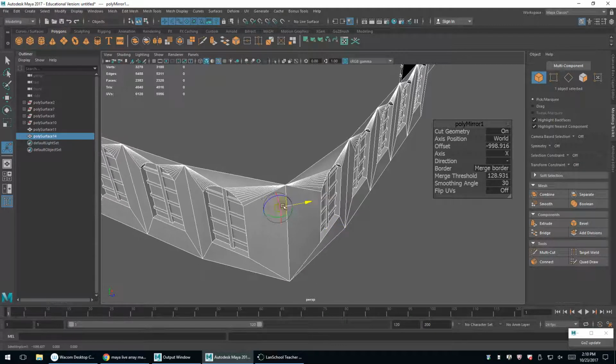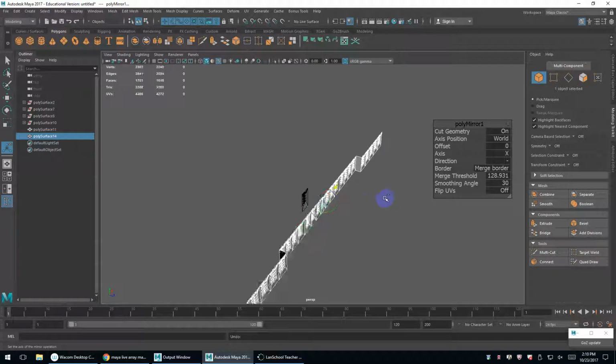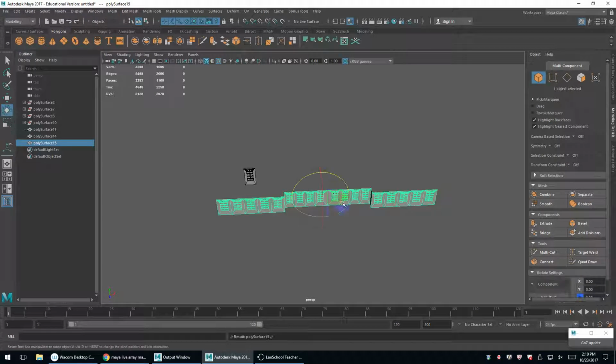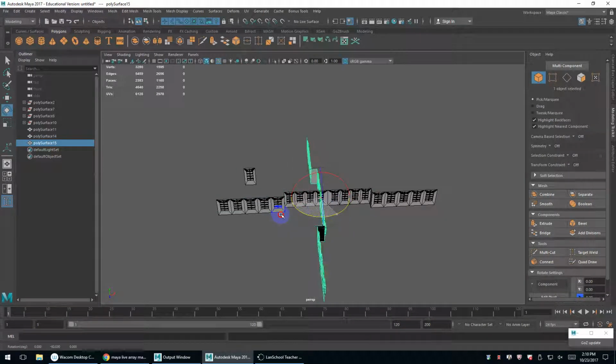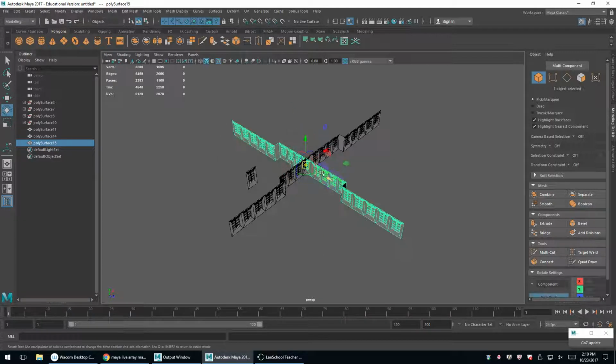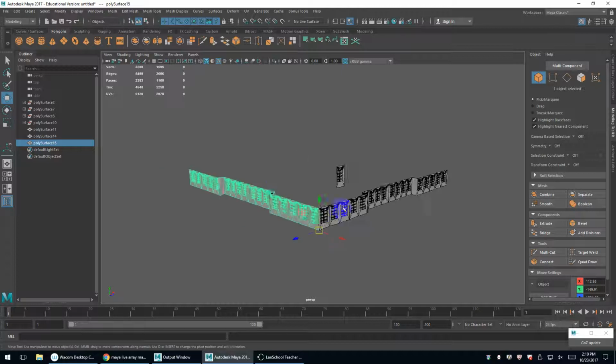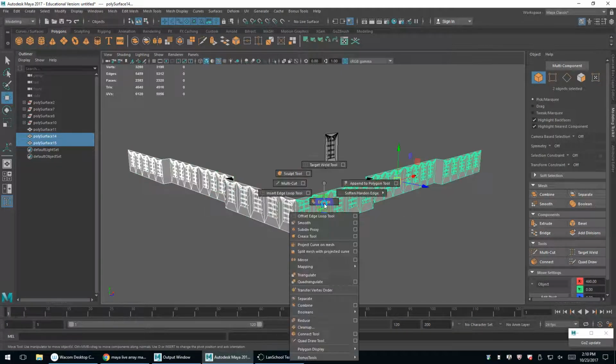Now again, this thing can get a little messy. So in some cases, it might just be better, instead of using the mirror tool, I might just hit Control D to clone this thing and do a standard rotation, right? And then if I hit the D key again, hold V, snap this out here, turn off D, switch to the move tool, hold V again, and then I can snap to that corner. So this is one way you can very quickly build a building.